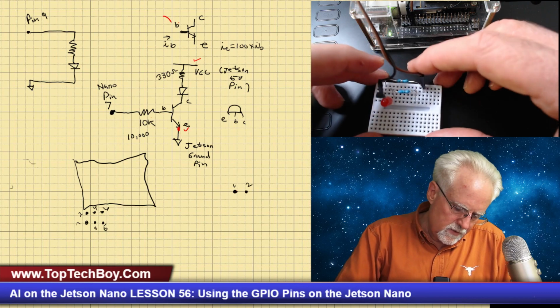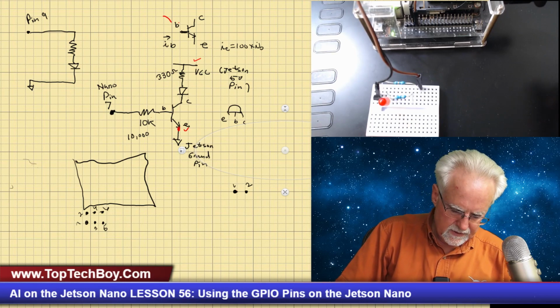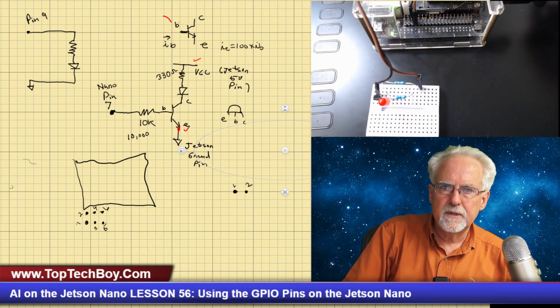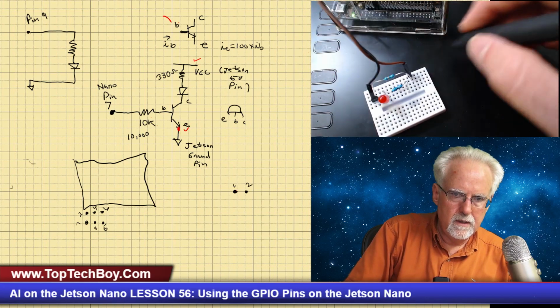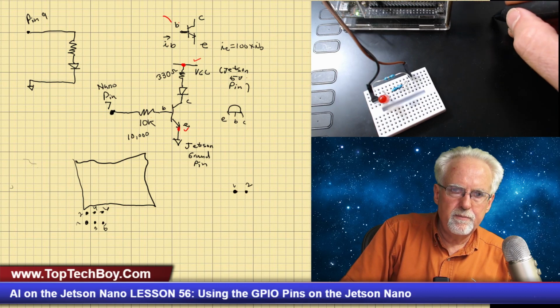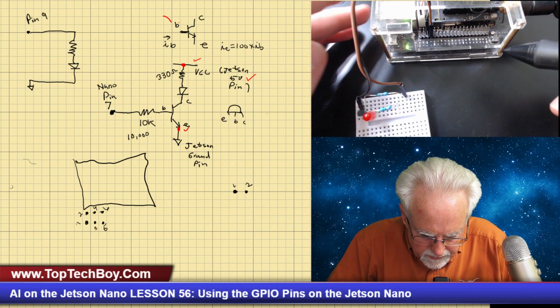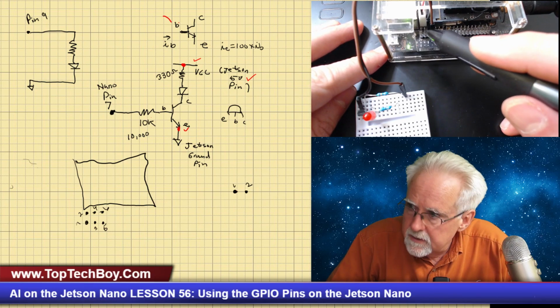All right, and so now I need to take the top of the collector going to the diode going to the resistor, the top of the resistor. I got that silly thing again. Okay, now we are up here, and that needs to go to VCC, which is pin 5 on the Jetson Nano. And let me show you how, or it's not pin 5, it's pin 2. Okay, pin 2 is the 5 volts.